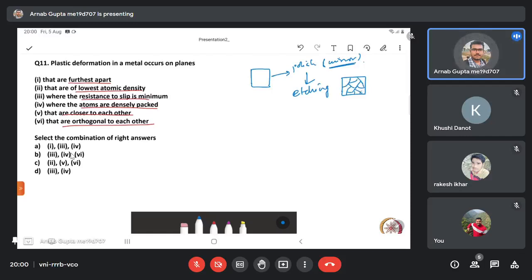After polishing, you have removed the film, but after this etching, these boundaries will be visible because this etchant will do selective etching along these boundaries. More material will get etched away at the boundary since there is less material present there. So if you are viewing this under a microscope, you will see this type of structure. It can be a different form also. It can be like this.